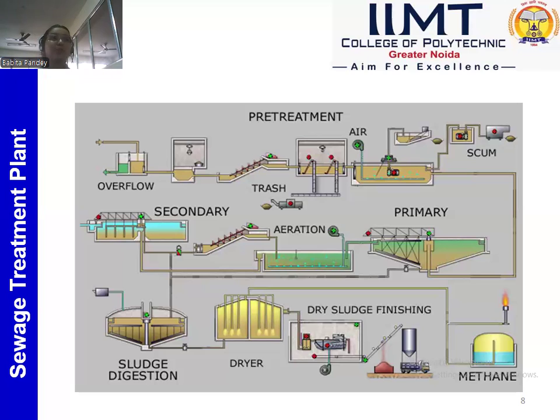They will ask for BOD. So definitely we will give the BOD. Once they ask for the BOD, oxygen is provided to them with the help of an air compressor. Now the oxygen is applied to the microorganisms, so they will function very nicely and decompose all the organic matter.